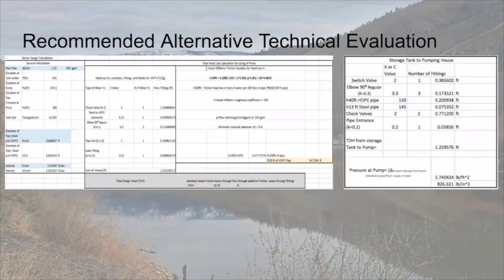So once we figured out all our preliminary designs and what constraints we had to deal with, we went into a technical evaluation, where we only had to use one major equation: the Hazen-Williams friction equation for total head loss. This was how we found the sizing we needed on our pump to deliver the water from an elevation of 245 feet to an elevation of 280 feet.